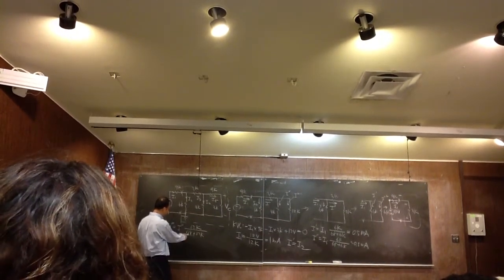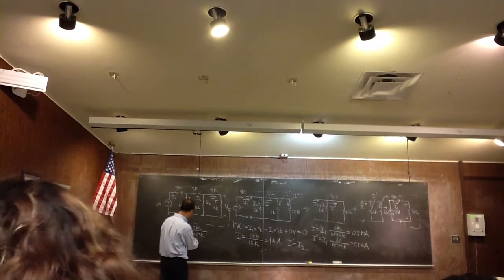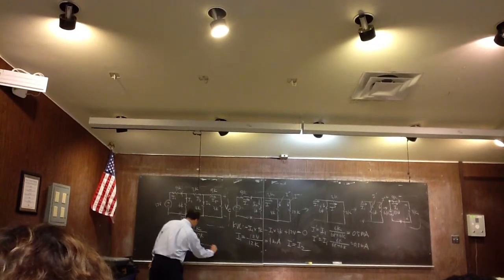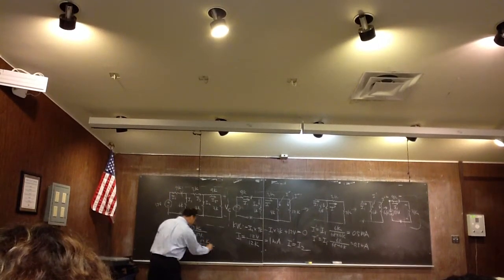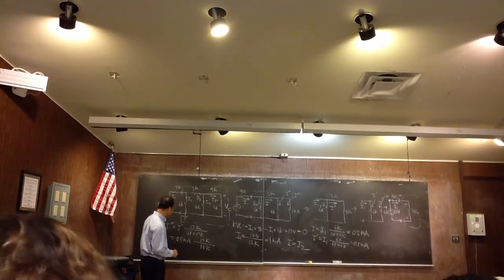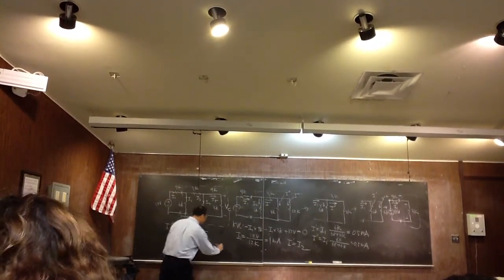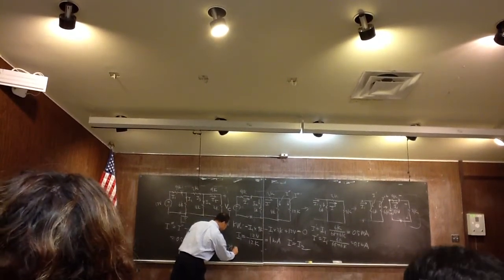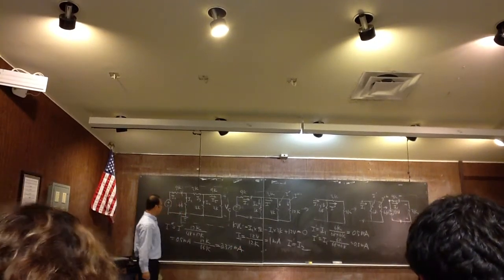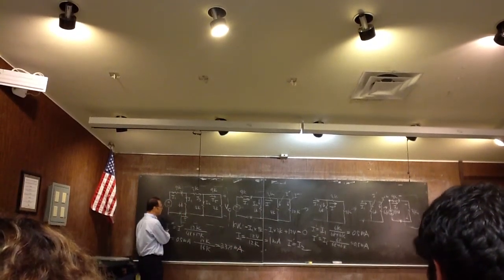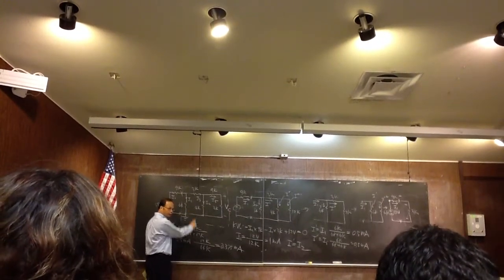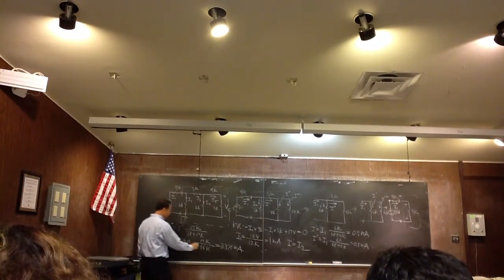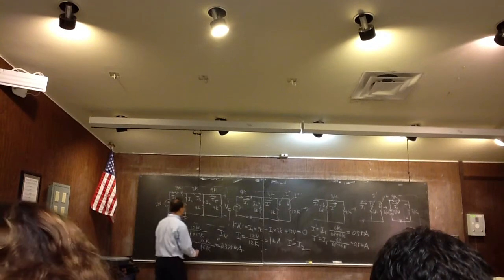And that, I don't know what that is. You have to do equations. Right? So this is what? This is 0.5 milliamp times 12K over 16K, right? So what is it? Point what? 0.375. I double prime going down to 16. Right? Okay, then what is that current in the original circuit? I4, that's right. So that is equal to I4. Yeah?